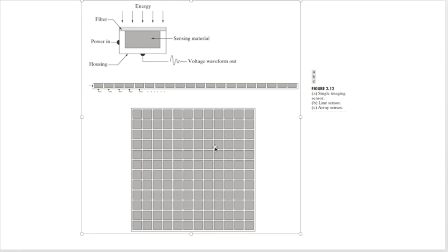All right, so this sensing material is most likely going to be CMOS, and you've got two options. You either have this kind of slow build-up one. This is often done with an older technique called charge-coupled devices. But basically, both of them are using semiconducting materials. Charge-coupled devices are usually a little bit bigger, and it allows them to kind of build up charges and go. They're more expensive. It's kind of one of those weird things, an older thing that's more expensive. But it is often used in a lot of astronomy applications.